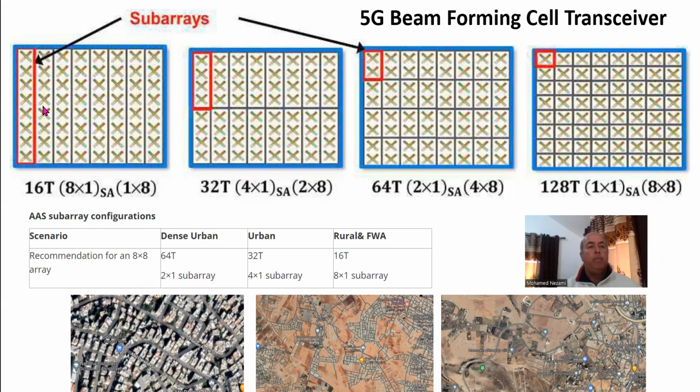So you really need a big beam, but not necessarily a lot of transceivers, because there is no demand for data rate. That's basically a case like this where you have 8 elements by 8 columns, and each one of these is connected to a transmitter. So you've got 8 transmitters, 8 receivers for every polarization. So that's 16. A case like this would work very well for the rural areas where you have 1 by 8. All you need is 1 by 8, and each one of these you would point to a certain section, or you could displace these beams uniformly in 360 degrees.